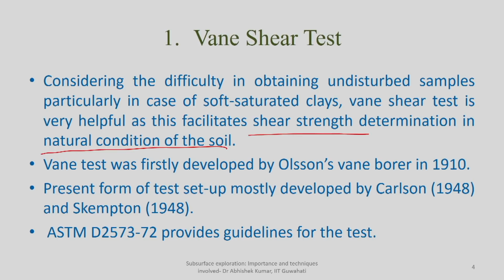The test was first developed by Olsen, the vane borers, in 1910. The present form, in which we do the test, is mostly developed based on the work by Carlson in 1948 and by Skempton in 1948. So whatever vane shear test setup, interpretation, and standardization we see here are mostly based on the work by Carlson and Skempton, both conducted in 1948. ASTM also provides guidelines in ASTM D2573 to do the vane shear test at your site of interest.